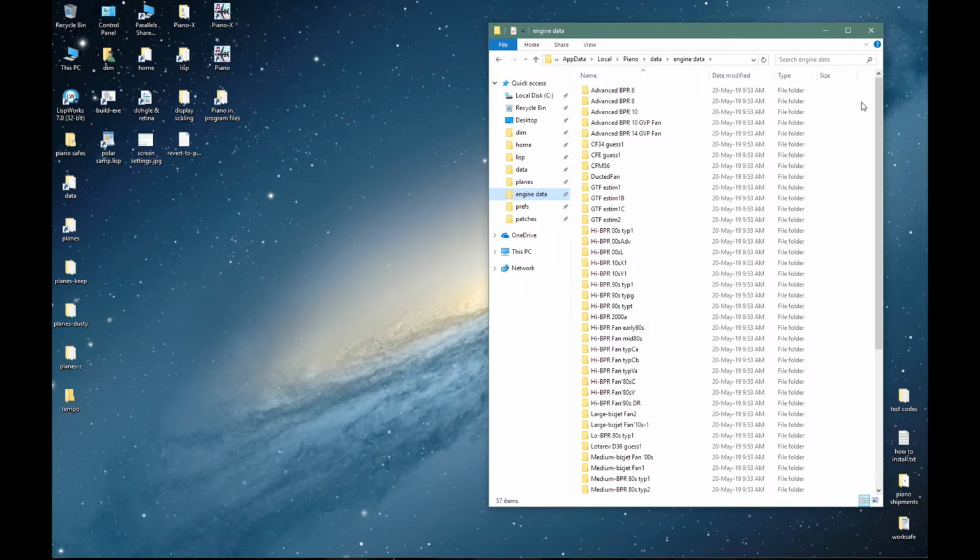One engine can be used by many different airplanes, adjusted individually by factoring the various ratings and fuel flows up and down to represent different related engine types. And you can also add new engines if you have access to the relevant characteristics.